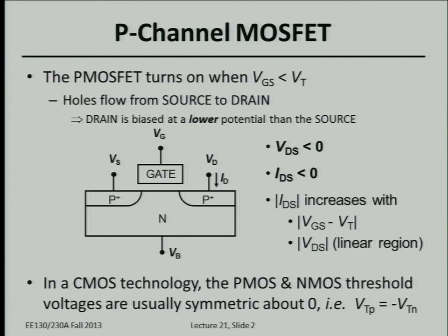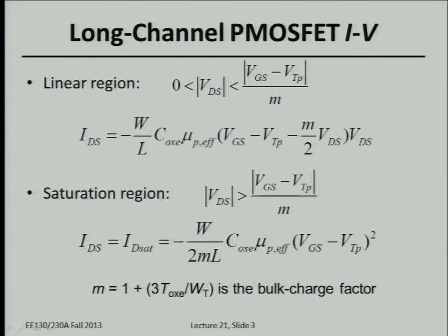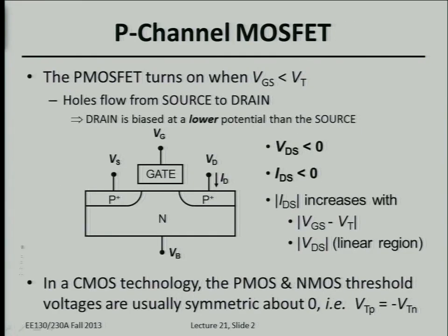analog circuit applications. So a P-channel MOSFET operates in a similar manner as an N-channel MOSFET. It's just that when you turn it on, you have an inversion layer of positively charged mobile carriers at the surface of the semiconductor. When you turn it on, there are holes that are sort of attracted to the surface. Actually, not attracted to the surface.